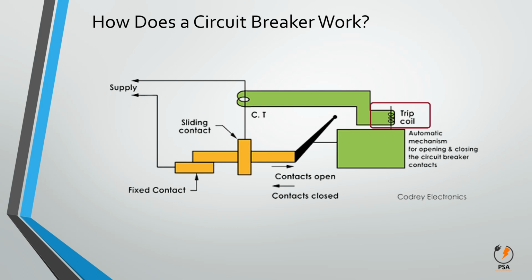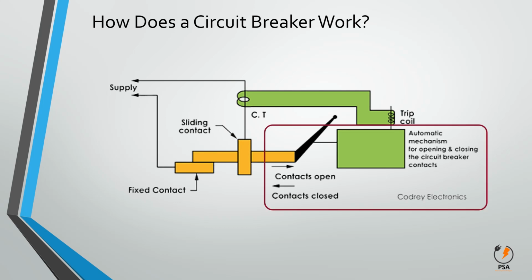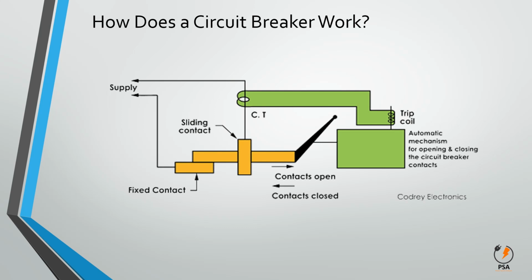All circuit breakers have operating trip coil and closing coil, which are energized by a switching pulse and displace the plunger inside. The plunger of this operating coil is usually connected to the circuit breaker operating mechanism, which releases the mechanically stored potential energy in the operating mechanism in the form of kinetic energy that sets the moving contact in motion. As these moving contacts are mechanically connected to the operating mechanism by a gear lever arrangement.